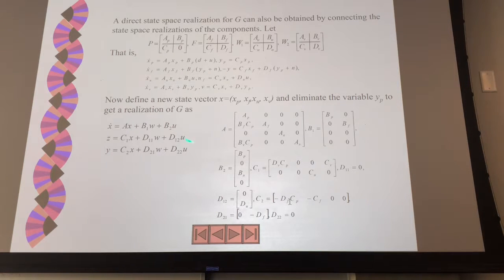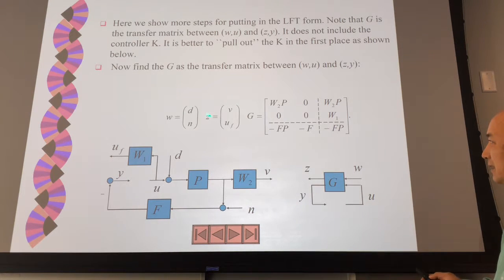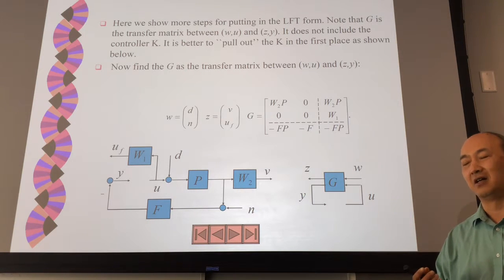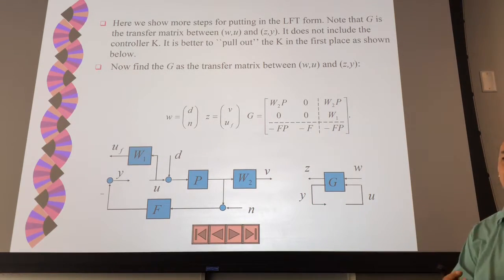But anyway, in the future, we will see your state equation, output equation, and performance assessment output, or filtered output for performance assessment, Z. So again, the Z is W_y and U_F, the filtered output and filtered input, constructed as a Z for my performance measurement. Performance measure, the output and control effort together. So if I don't care about control effort, you can set W1 to 0, okay? Makes sense?